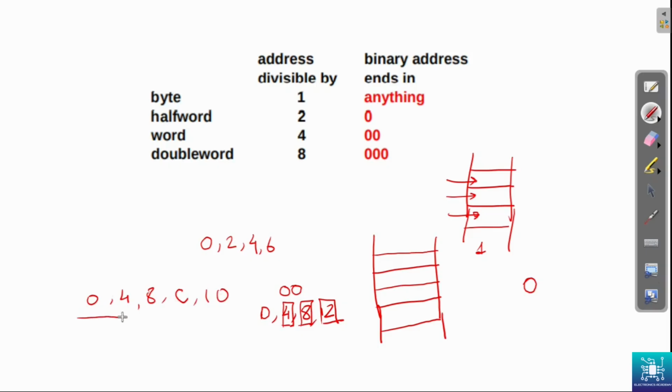So this is how the addressing will progress in the case of a word aligned address location. For a 32-bit controller it is always easier and faster to access word aligned boundaries. If the content within the memory is word aligned, it is much easier and faster for the processor to access it.